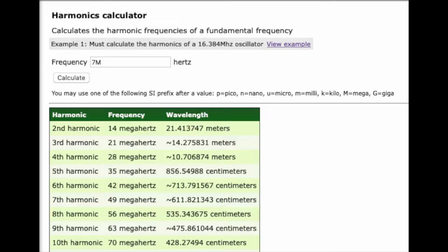So you know you've hit your bandwidth when you're scoping or probing a signal, and you see that you have dropped your amplitude down to 0.707 of what it originally was at the fundamental, but that's for a sine wave. So again, your square wave is going to round off to a sine, and then you're going to start decreasing in amplitude, and you'll get incorrect amplitude measurements.